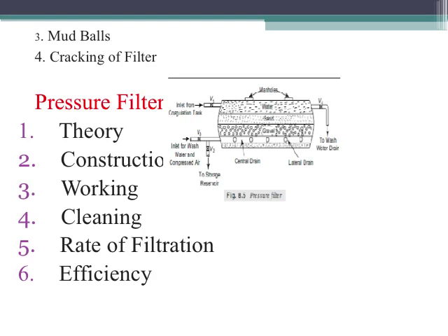So, what are the uses of rapid gravity filters? They are best used in the case of public supplies and are the most economical in comparison to slow sand filters. They are especially used for the municipal supplies of large towns and cities. The treated water is, however, not so safe and needs some disinfection. That means it needs further treatment before it can be supplied to the general public.